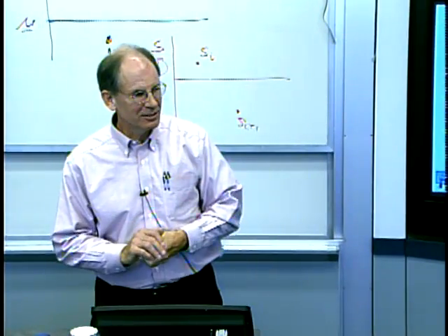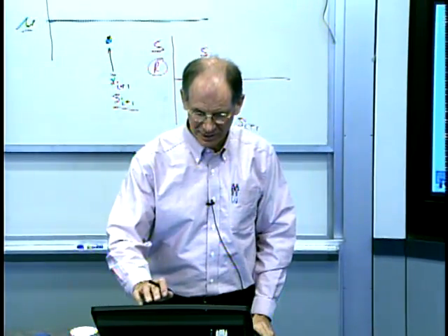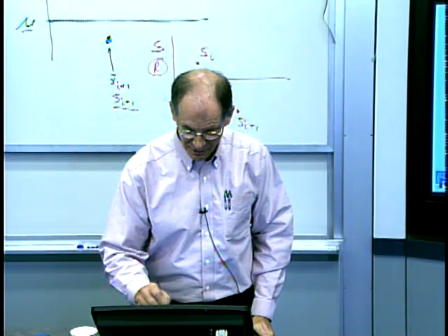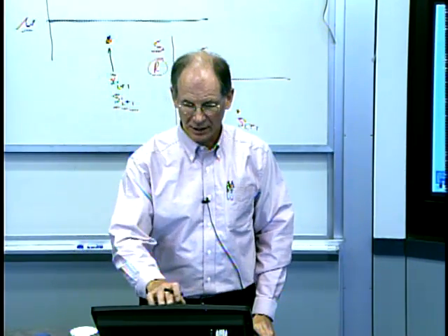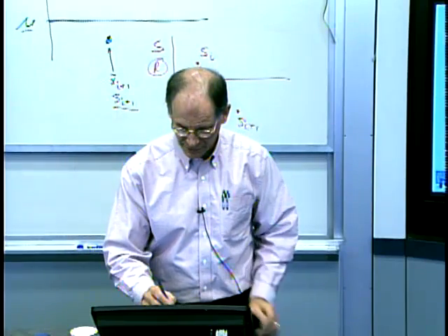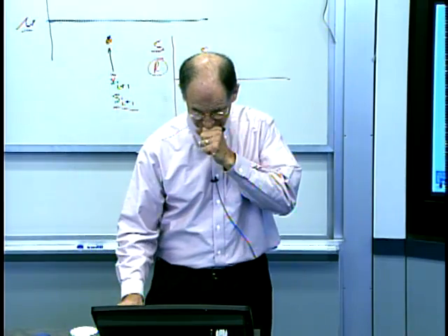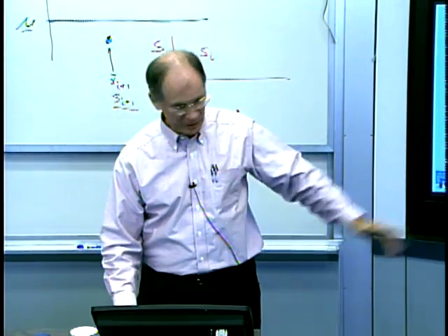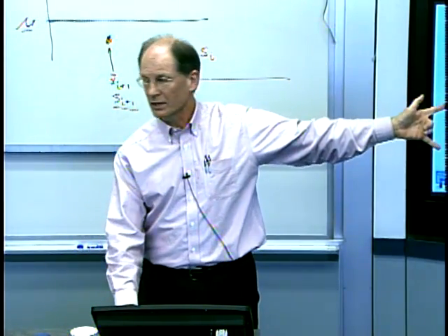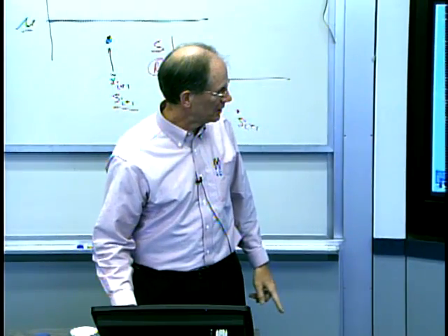But it's a little bit simplistic, because it is possible that you'd get a process that's perfectly in control and you'd have one point that's up here. It's just not probable, but it's possible. So we can do a little bit better than that. And again, we can do the same thing with the S chart. We can do upper and lower control limits.